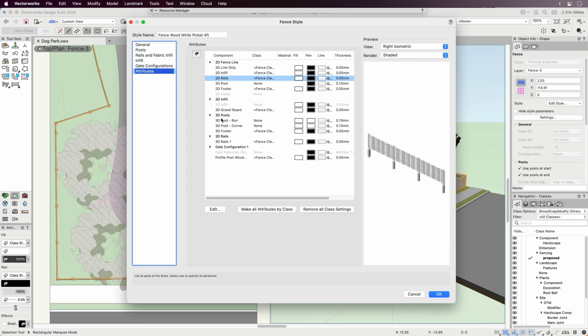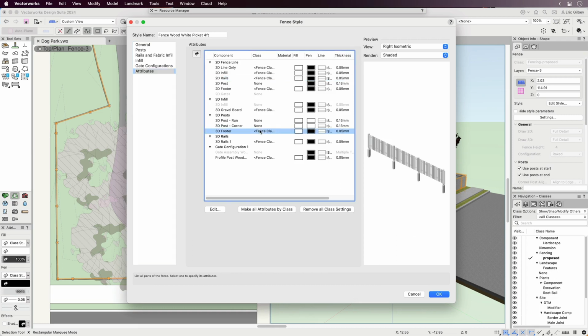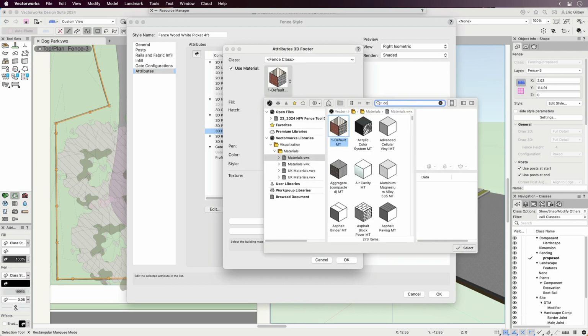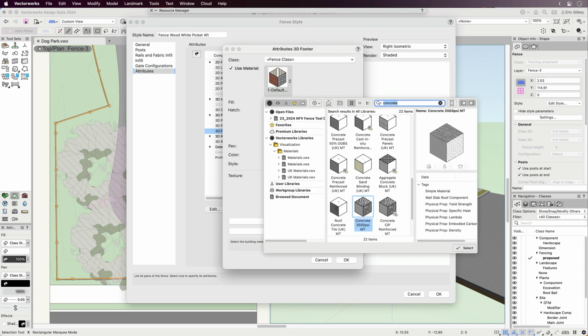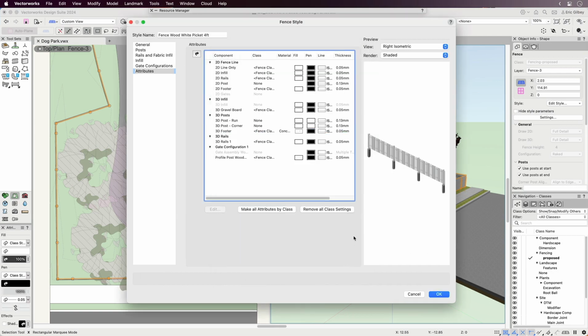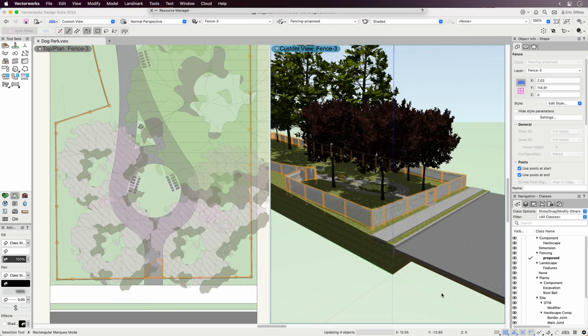The best location to customize fence materials is through the Attributes dialog within the fence settings. Here you have the opportunity to use class settings for each fence part or use assigned material settings. If your eventual goal is to report not only the parts but the materials as well, it will be worth the short time spent assigning these attributes.